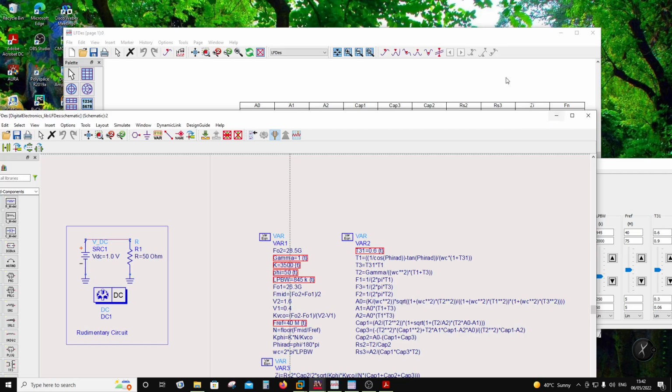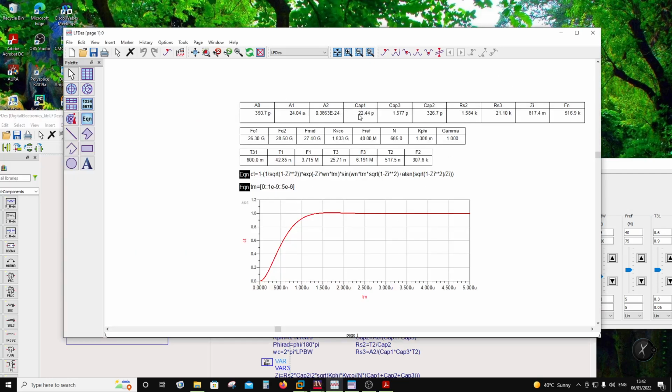So if you look at the loop dynamics, what I have come across is this is the loop filter values, right? So basically these are my loop filter values here. This is the loop filter values which I'm going to stick to, and here the K phi is 1.3 milliamps of current, because I have split the band into two, and my tuning range on voltage is from 0.4 volts to 1.6 volts, right, from a supply of 1.8 volts.